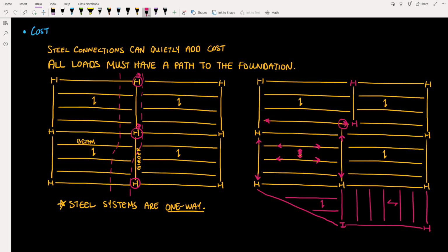Additionally, you can see down below here I have added this slanted beam. And here you can see that these angles are not 90 degrees. Ideally, with structural connections, we want to keep our angle at 90 degrees, as this makes welding elements much simpler. Connecting to an angled beam like this creates a skewed connection, which can also add cost to the project.